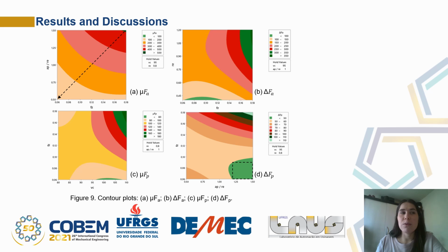Smaller force values result from low levels of cutting speed, depth of cut, and feed per tooth. These combinations correspond to a smaller cross-section, which agrees with the theory presented in this study and the results obtained through variance analysis. The influence of cutting speed on the static portion of the active force could also be seen.